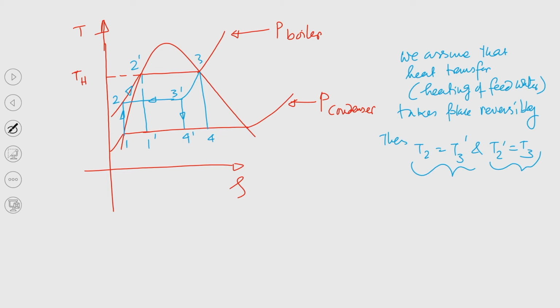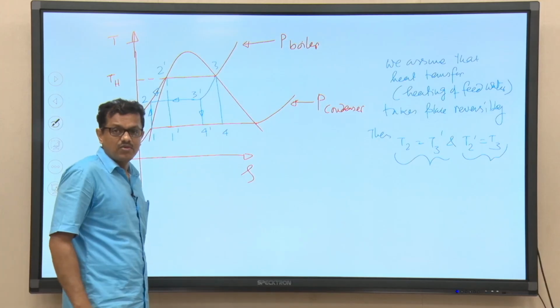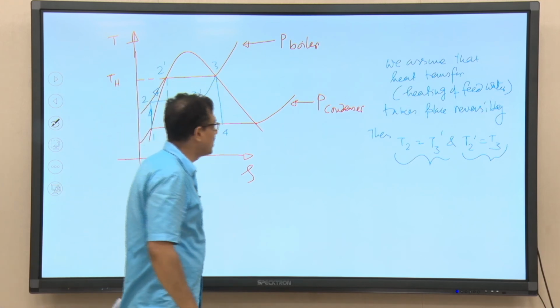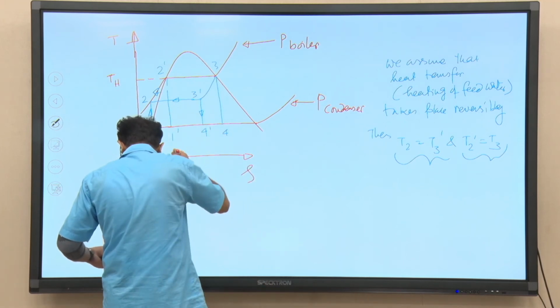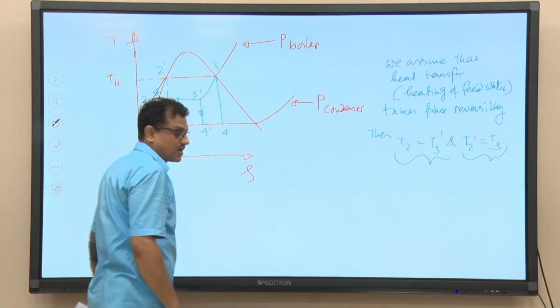Okay. So, that is, if the process is reversible, then at any section, if we draw a line, at any point steam temperature must be equal to the water temperature, right, quasi statically, almost they are in equilibrium condition, right. So, that is the concept you have studied in thermodynamics. So, at any point between the heating and cooling process, temperature of steam and water will be equal, and as a result of which you know that the path followed by steam will be exactly equal to the path followed by the water, right.